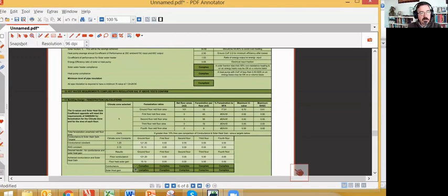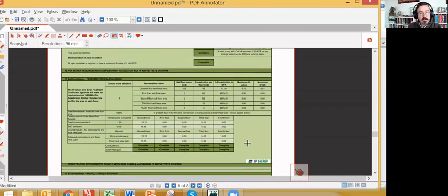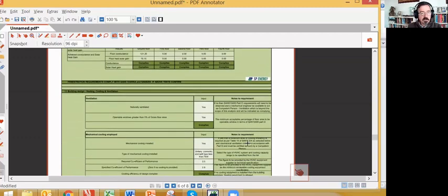So here we can see the results of the fenestration section printing out with critically the U value and the SHGC requirement, which your builder would need to go to fenestration or the aluminium and glazing industry to ensure that the specifications are met.